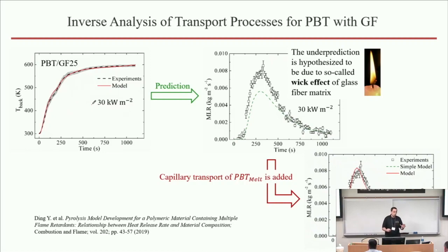Now, I do want to point out that we are still really learning how to parameterize pyrolysis models that do both things well, okay? We are nowhere near the point where we have a well worked out workflow for a model that does both burning and oxidative pyrolysis or smoldering well, and things in between.